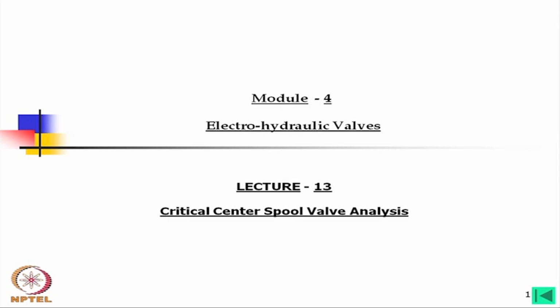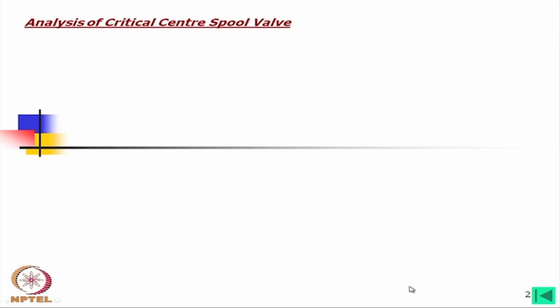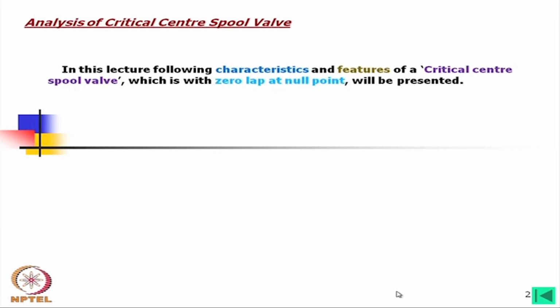Welcome to today's lecture, lecture number 13, critical center spool valve analysis. This is under module 4, electrohydraulic valves. Now, in this lecture, the following characteristics and features of a critical center spool valve, which is zero lap at null point, will be presented.